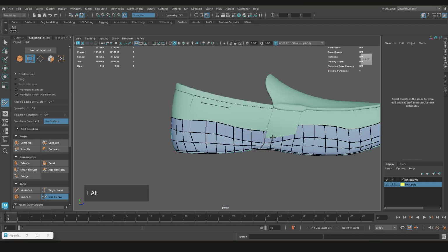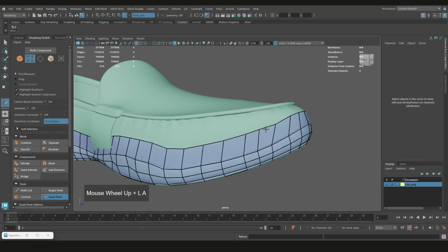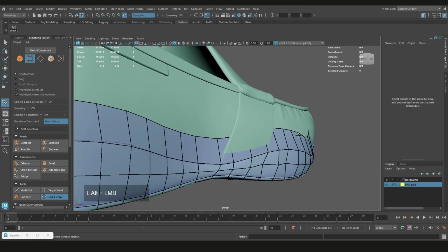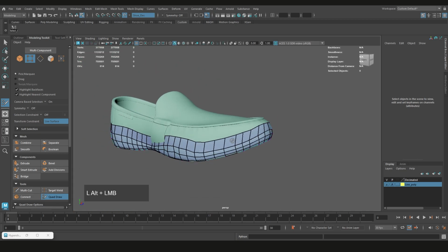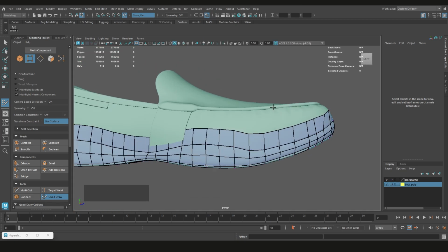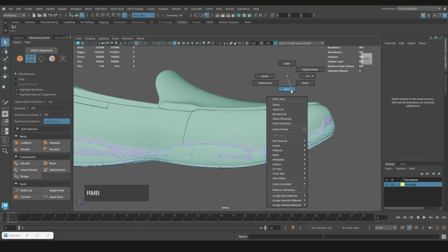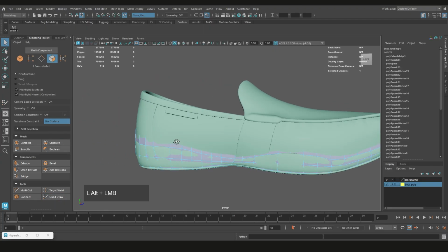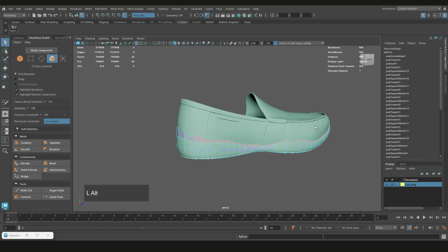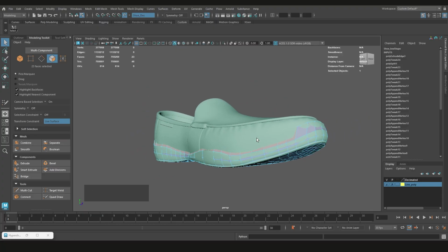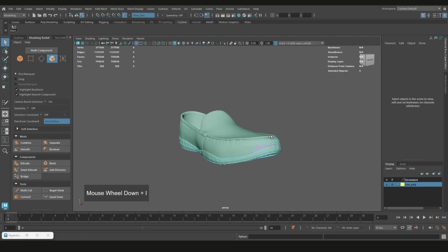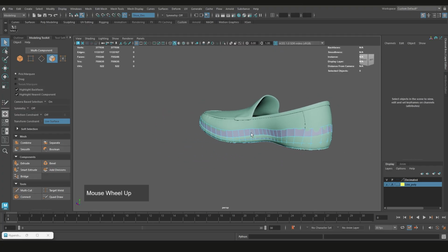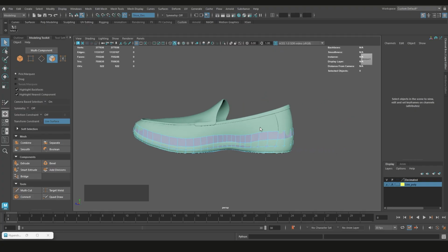Okay, so that's all I'm going to do next. So nothing too crazy again, right? Just following a sort of procedure, right? And that's really all it is. And again, if it's clipping edges like this, which it will, right? It just will, that might annoy you. So I'll just go to Control-Shift-Q, go to maybe face, for example. Okay, and then click, and then Shift, double click. That'll get the loop from here to here. Then I can just delete it, right? And then do it manually. So whatever you want to do, up to you. So yeah, I'm just going to fast forward through this and we'll just keep going as we go.